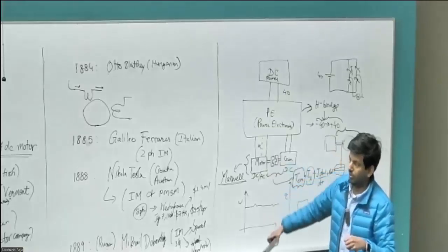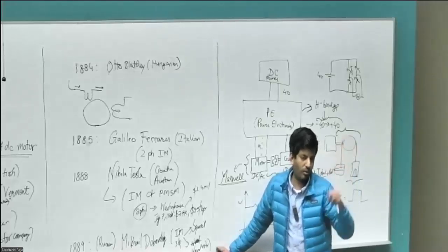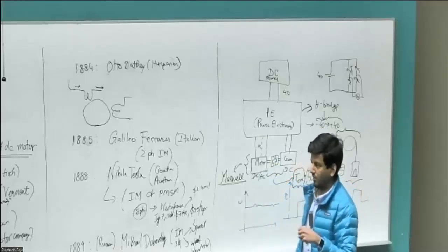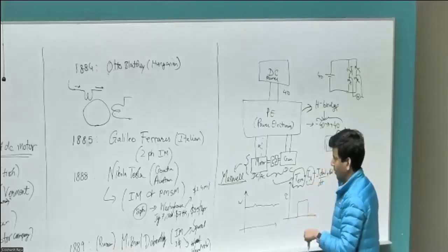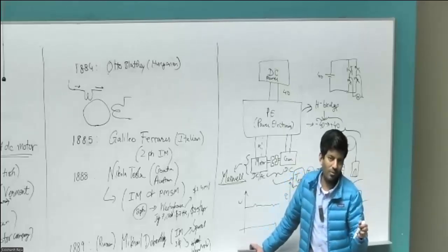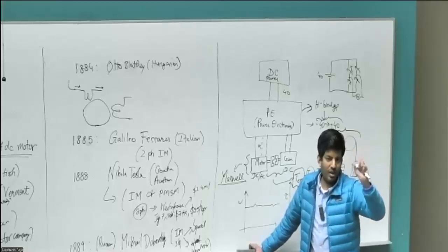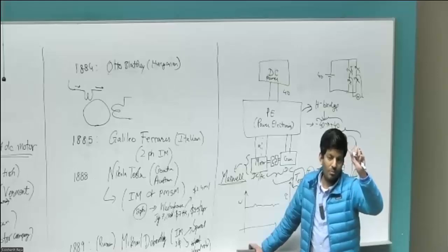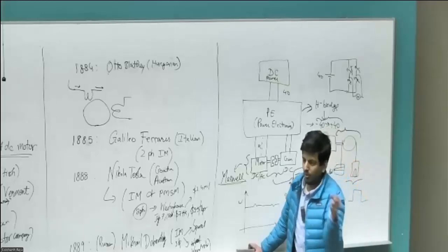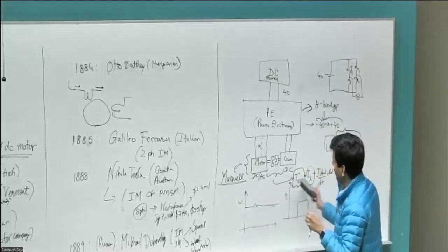Because we saw that DC motors and induction motors don't have the same characteristic, right? They all have the speed drop if the load torque increases. So how do we circumvent this characteristic? By putting a controller on it, which can overcome these limitations that are found within the motors themselves. So we'll look at how to design these controllers, and we'll also see how to do torque control, typically used in traction applications, or how to do position control, like the camera that we have right there. I ask it to go to a particular angle. It's basically having a controller with a DC motor or a permanent magnet, be it a brushless DC motor, which does some kind of control and goes to whatever angle I want it to go, or a robotic arm in an assembly plant and so on and so forth. So we look at all of those later, but we need these three fundamental tools to build on top of.